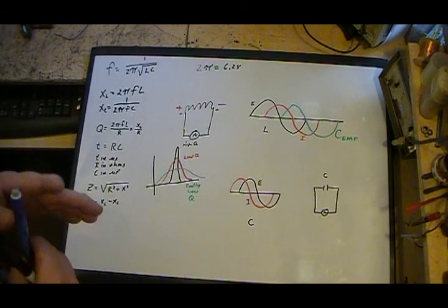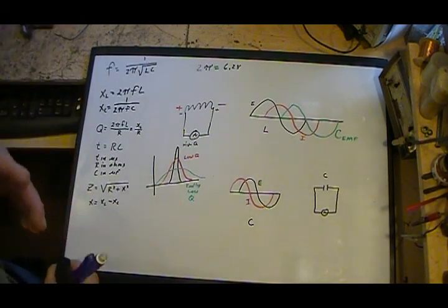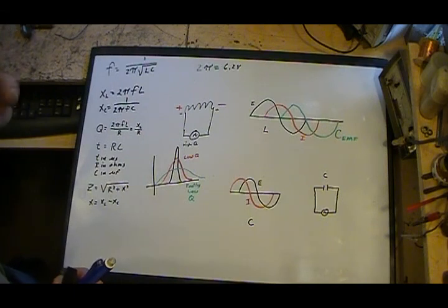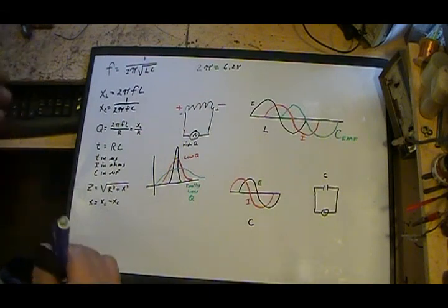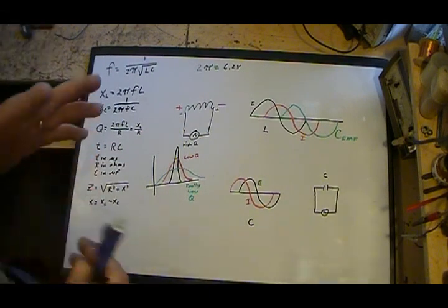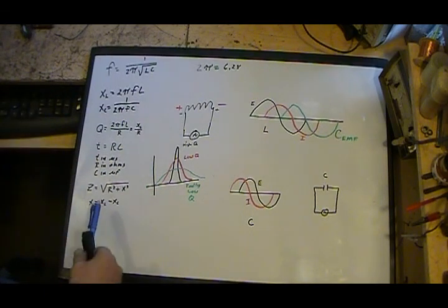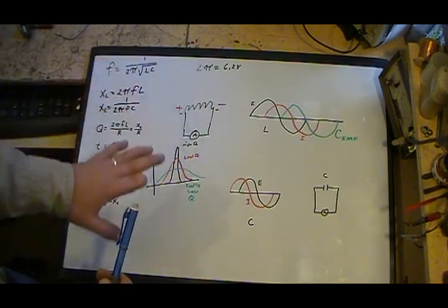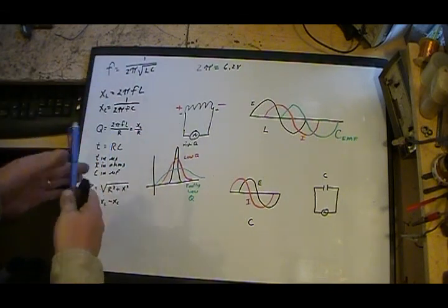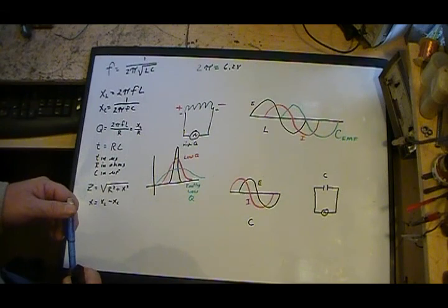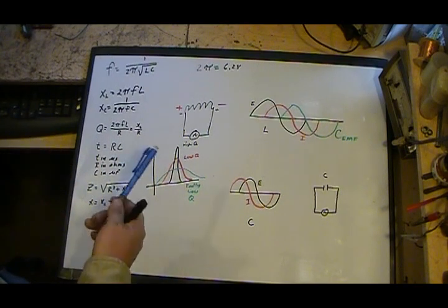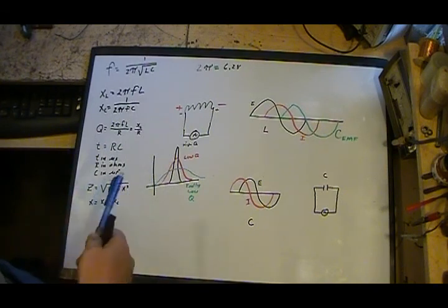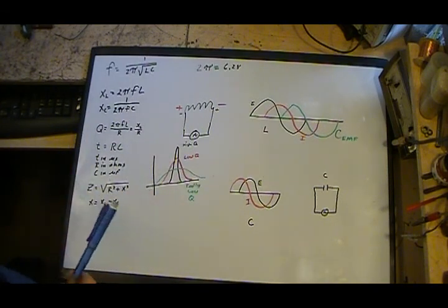And that works for everything, whether it's the impedance that you're looking at going into a tube, like the input of a tube at the grid circuit, or the plate impedance, cathode impedances, filter impedances, and so on. This can actually be pure resistive. You can actually have no capacitor or inductor, and have nothing but just a resistor, and then it just works out to the square root of R squared, which is just R, so your impedance just ends up being the resistance.